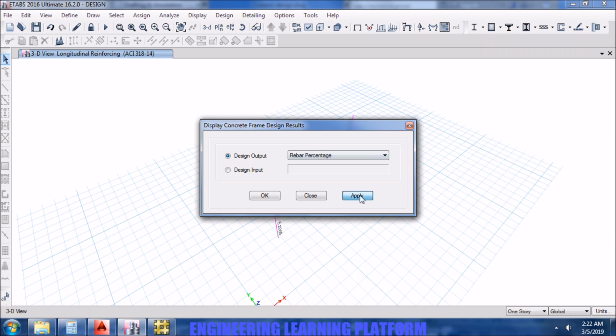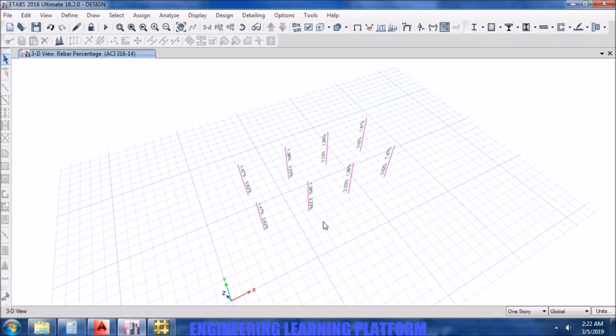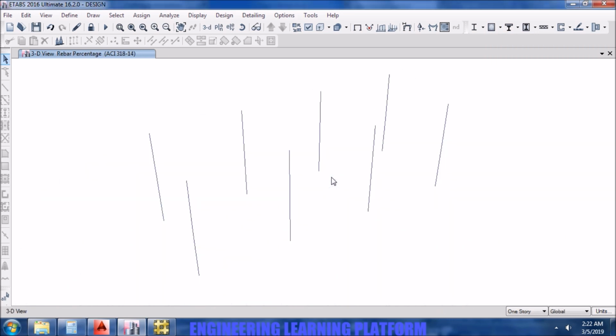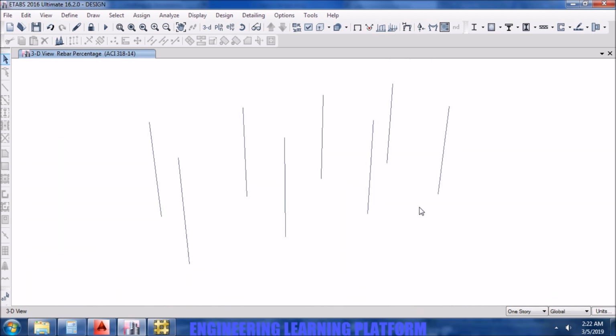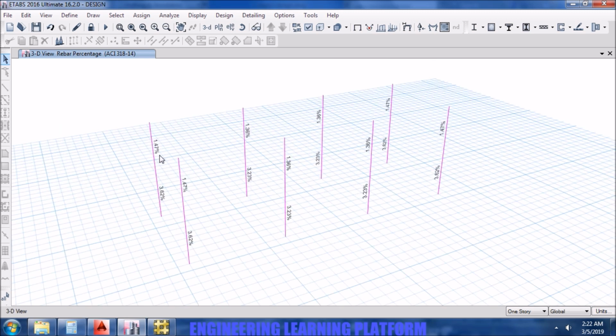So we are getting a lower percentage of steel than the exterior column since it's a sway moment resisting frame. If it was designed only on gravity loads, then logically we would be getting a higher percentage of steel in the interior column since the column catchment area is higher.